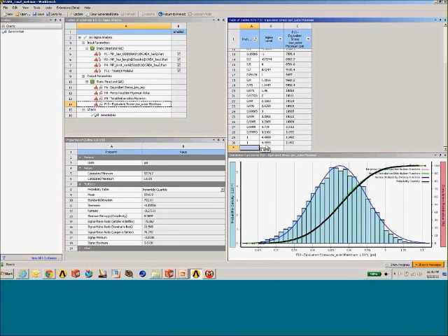The Six Sigma approach takes into account a 1.5 sigma drift. So this 4.5 sigma with that 1.5 drift would give me a 6 sigma stress. What that says is that 3.4 in 1 million parts may see a stress of 11,492 psi or better. If that 11,492 psi stress meets my stress criteria, then I can be confident that I have a robust or a 6 sigma level of quality in my design.